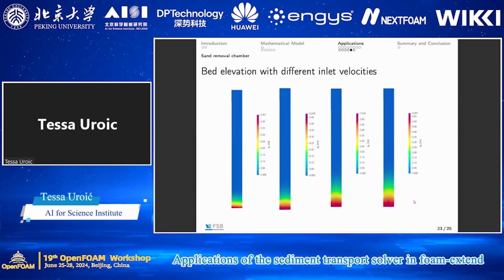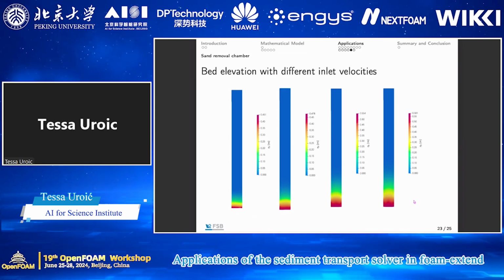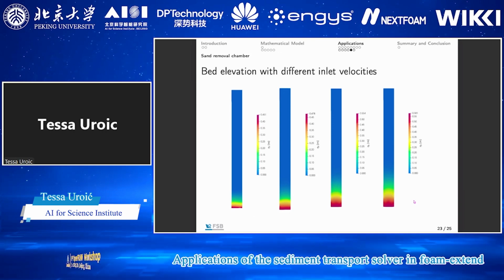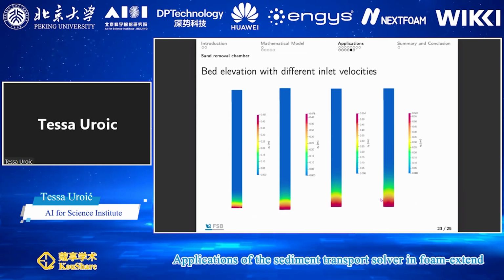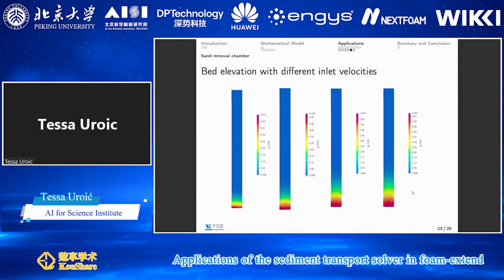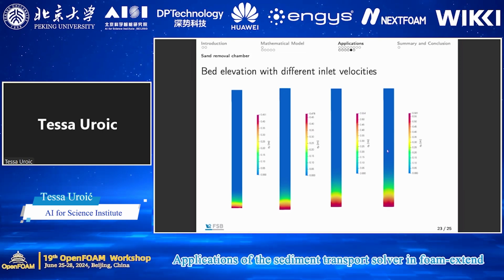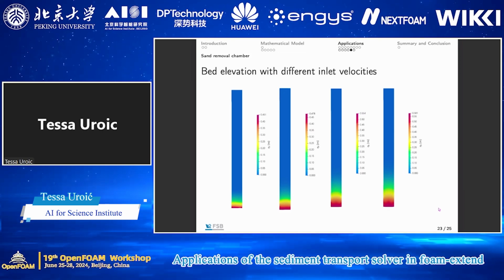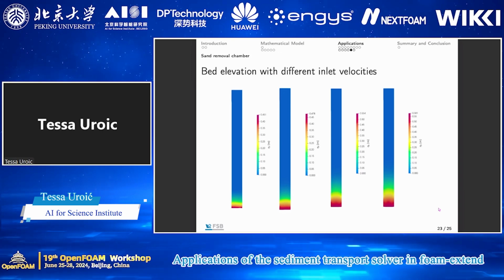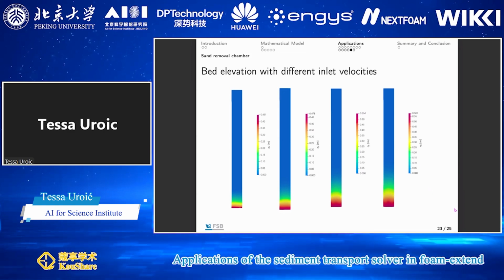The second thing that we tested, as I mentioned, was the inflow velocity. We expected that large inflow velocities will affect the sedimentation process, since convection will carry the particles further away. And this is exactly what happens. If we go from left to right, the velocity values increase, and you will see that the bed elevation is quite high if we go alongside the axial direction of the descender. So if there are high values of velocity in some flow in a stream, the descender should be quite long for the sedimentation process to be successful.